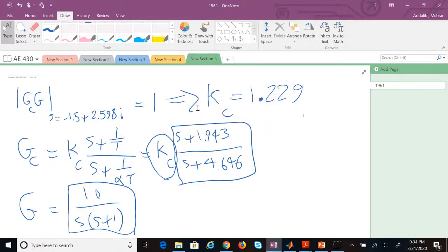That zeta is equal to 0.5 and omega n equals 3. How about we look at the root locus of the original system versus the root locus of the new system, and confirm whether this newly added lead compensator, when combined in series with G, would give me what I really needed.